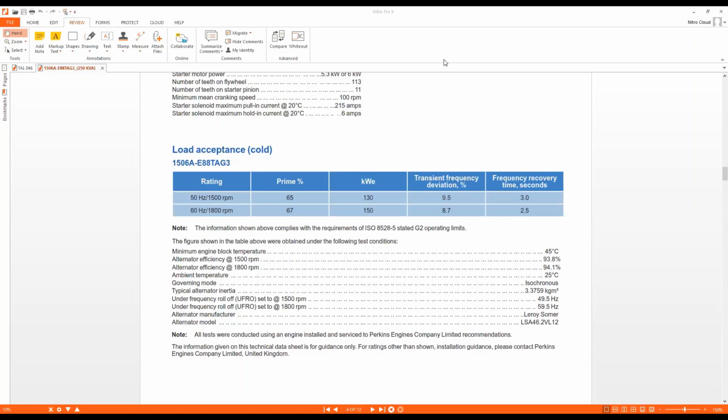I have one question. Is it per step load? What do you mean, is it per step load? Okay. Nadeem, what you see on the slide is the tip of the iceberg related to ISO 8528. ISO 8528 is much more detailed and much more thorough. And it allows for some engines up to 5 steps, okay? So this is per step load, considering in some cases 5 steps as per ISO 8528, but it differs from one engine to another.